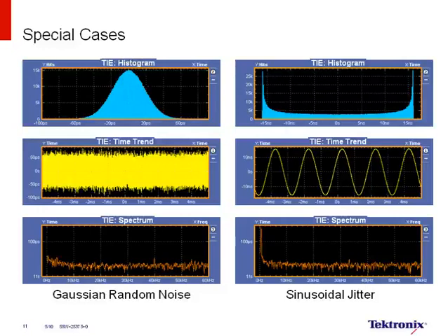That same view on a system that has deterministic jitter shows that it has a population that's distributed or focused on the edges of the histogram. So just looking at the histogram view will give you a very good qualitative feel for what the jitter sources are.